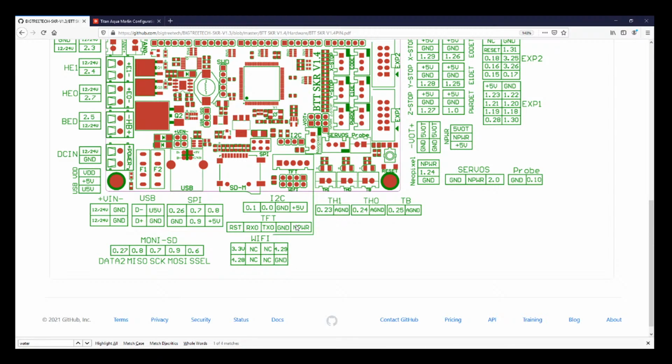So I'm going to power it back up. And I got to figure out what that is. So it looks like a long stripe. So if we look over on this side, we see a long stripe right here. So we're going to measure right there. So that should be 5 volts when it comes up. So I'm going to stick the probe over here. Stick the other probe, I think right here.